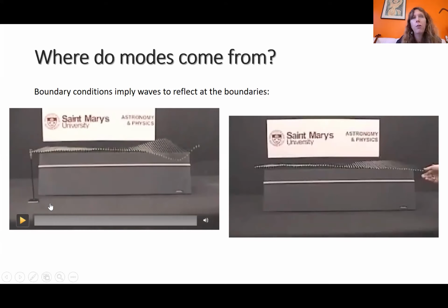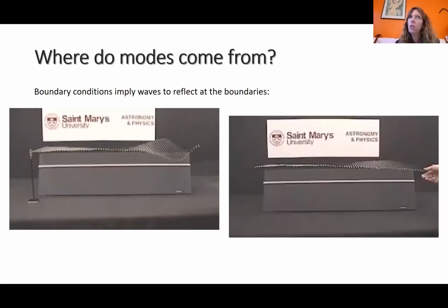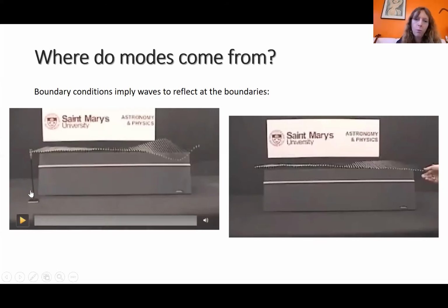The vibration of a structure will become nonlinear if you really excite it at very, very large amplitude. You never achieve such amplitude with the violin. At the range of excitation amplitude it is excited, like normal bowing or normal hitting, you are still in the linear domain. To reach the non-linear domain would mean actually breaking the violin into pieces, because you would excite it so badly that it would just be destroyed.